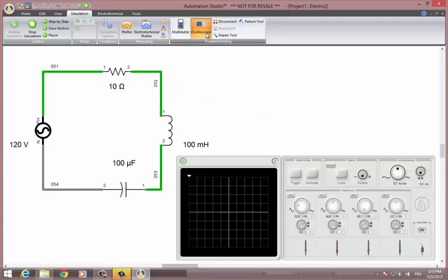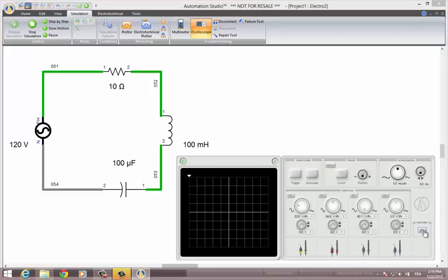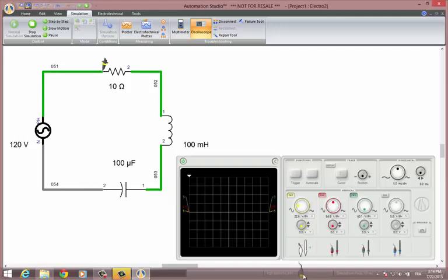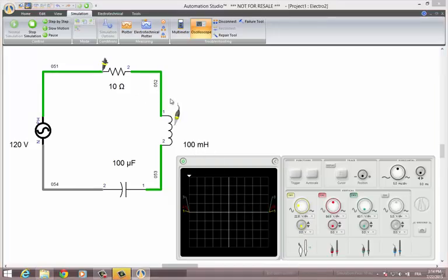Opening the oscilloscope, you will see that each channel has by default a single ground probe. By clicking this ground button, you can switch this option for having individual ground probes for each channel. Then you can turn on the different channels that will be required, and clicking on the probes will have them pop out and you'll be able to use them in your circuit.